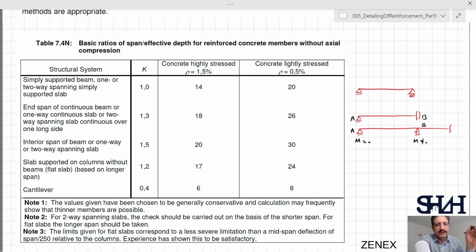It means that we are in the middle of the supports. As a result, both ends are taking some moments. Moment is not 0 in this case. The ideal beam in this case is like a fixed supported beam. Here you can see that at both ends we have moment and moment is not 0.